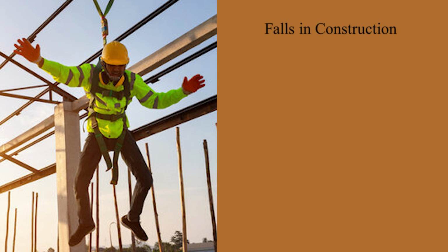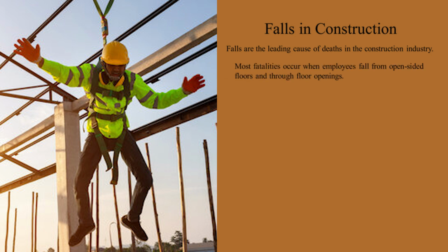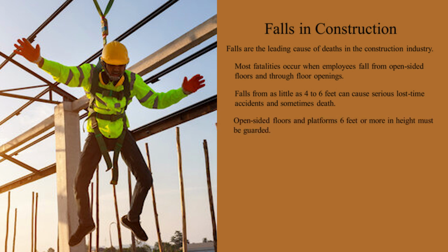Falls in construction: falls are the leading cause of death in the construction industry. Most fatalities occur when employees fall from open sided floors and through floor openings. Falls from as little as 4 to 6 feet can cause serious lost time accidents and sometimes death. Open sided floors and platforms 6 feet or more in height must be guarded.